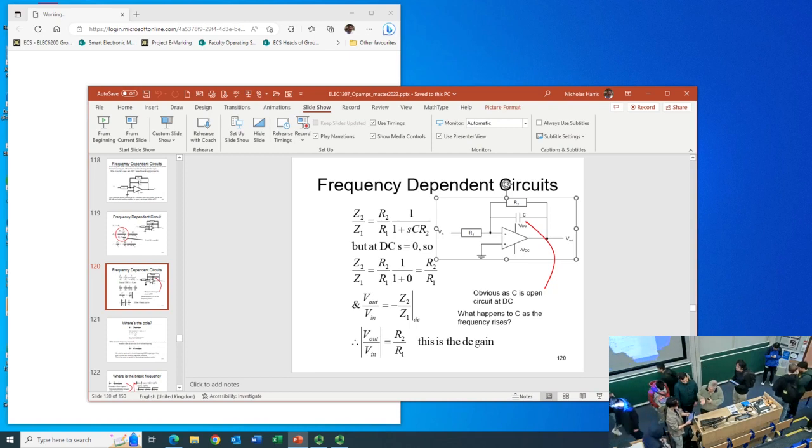So the phase is hidden in these equations if you're not careful. That's a phase shift of 180 degrees. It's an inversion. If you've got a signal that rises into the amplifier, you'll get a signal that's falling coming out of the amplifier, just bigger. It's opposite. Okay, thank you.